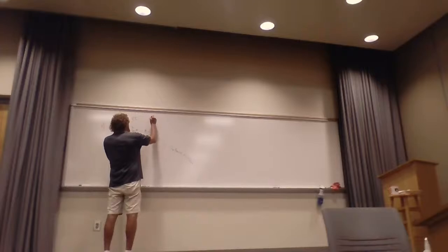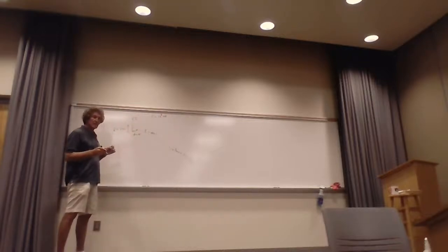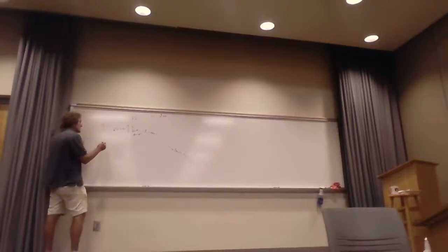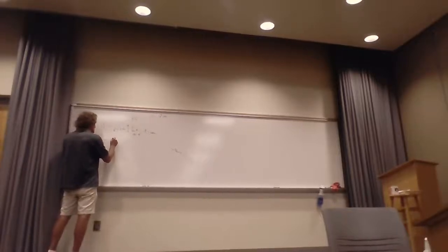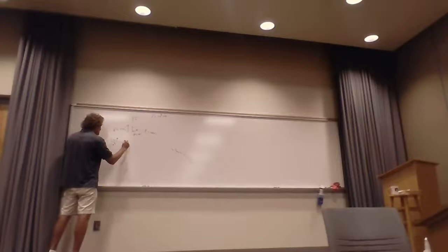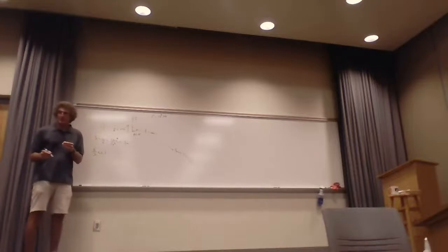And the frequency was, I think, 10 to the 8th hertz, right? Frequency is not given. It's at the bottom. Oh, yeah, it's in the second part. Yeah, 100 megahertz. So right off the bat, I can say the wavelength is C over F, or 3 times 10 to the 8th meters per second over 10 to the 8th, or 3 meters, and therefore L over lambda is much less than 1. It's a short dipole. It was stated it's a short dipole, right?